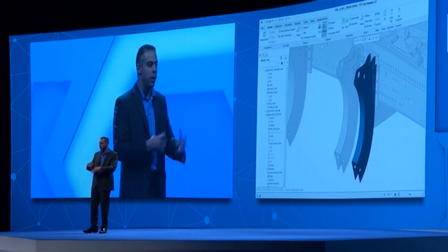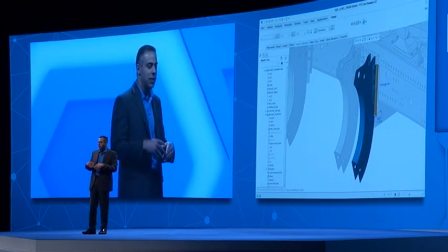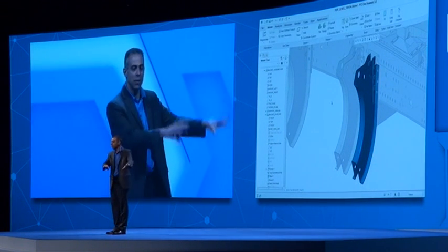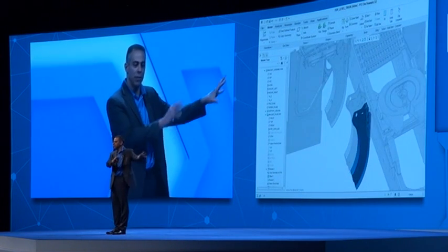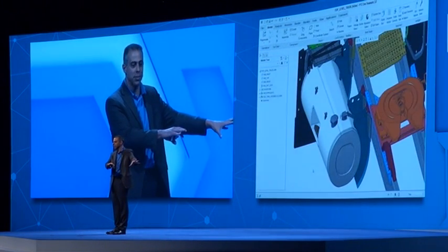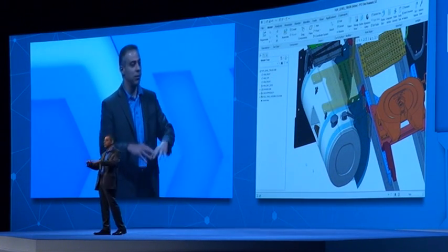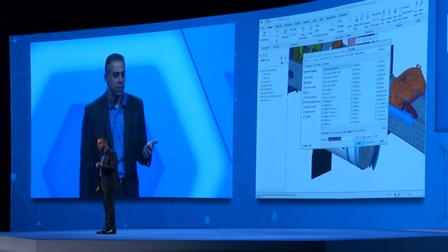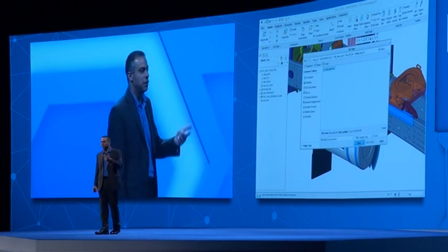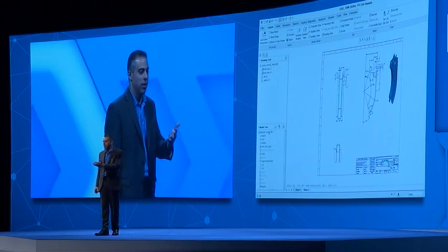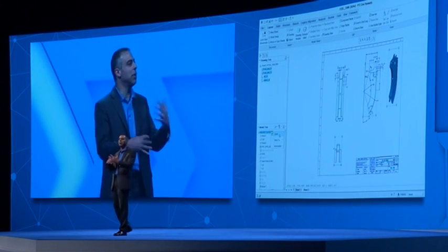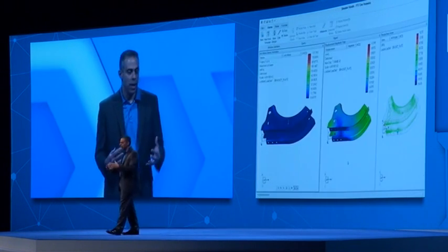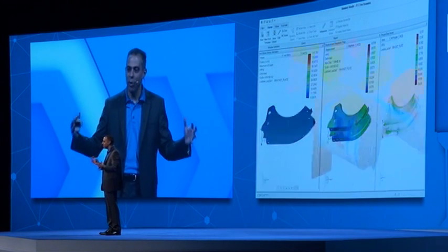So as I carry forward here, I've got a nice sheet metal object, I can carry forward my design, finish that sheet metal object out, and I can start building downstream deliverables off of that object. Now remember, I have a relationship to a SolidWorks object here, but it's robust, okay? So I can build downstream deliverables, I can build additional hardware, I can do things like build a drawing of this tank. I can build a drawing of the bracket that I've designed. There's the drawing of the tank, there's the drawing of the bracket. I can even do some preliminary simulation in Creo Simulate to start getting an idea of how this bracket's going to perform. I'm doing this all in the context of the design process.